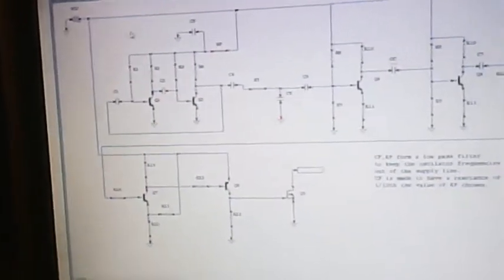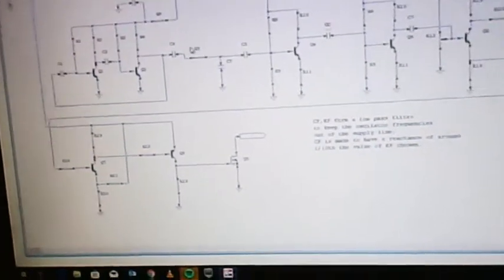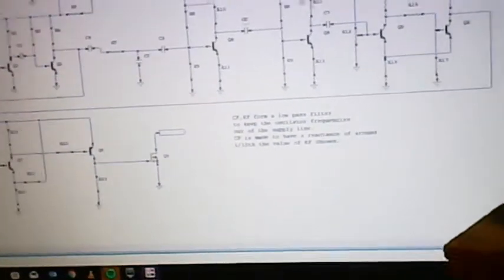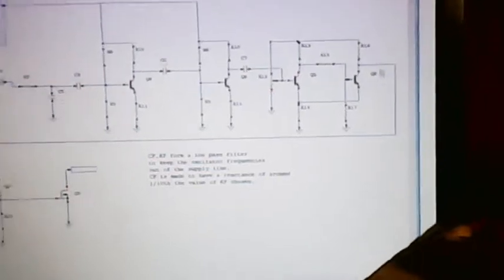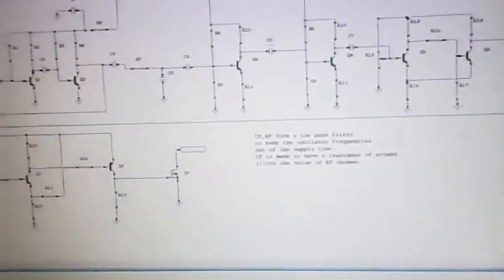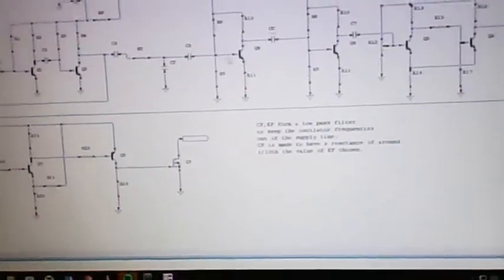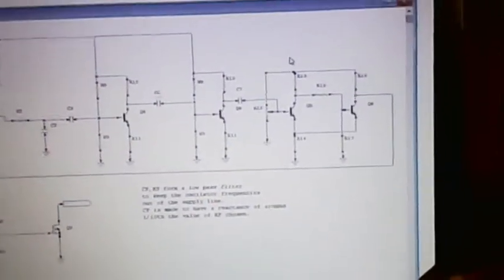Okay, this is the circuit that I'm working on right now. I'm experimenting and playing around with designing transistor pulse width modulation circuits. I have the astable multivibrator here, an integrator circuit, this RC low pass filter, a couple of amplifying stages, and then a Schmitt trigger circuit. That takes my square wave to a triangle wave, and then that gives me my pulse width modulated square wave out here to run a load.